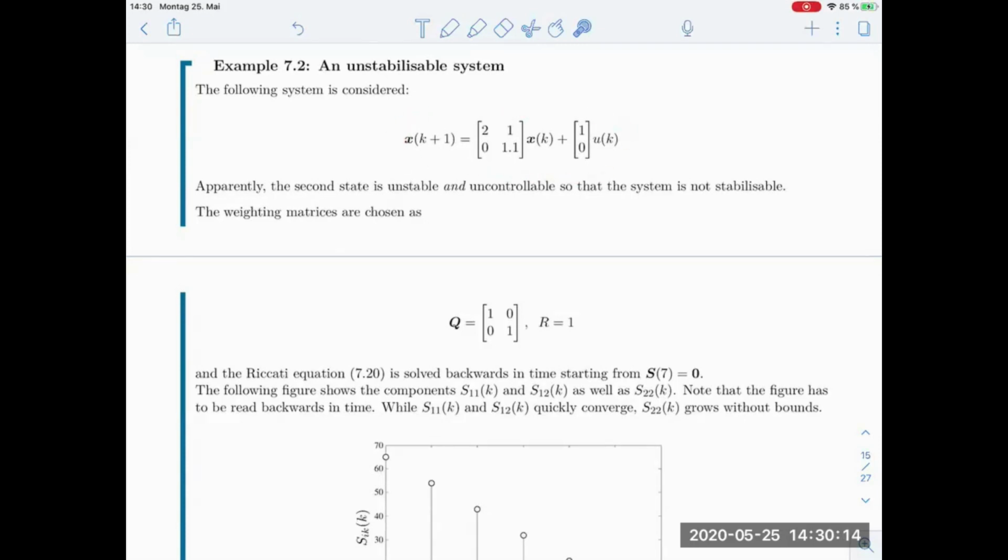We have this system. The system has 2 unstable eigenvalues. Well, how do I know that? Remember, we spoke about if a matrix has a particular structure, let's say A11, A12, a 0 block, which goes to the main diagonal, and then we have A22. Then the eigenvalues of such a matrix are the eigenvalues of matrix A11 union the eigenvalues of A22 because of this block of zeros here. All right, so that's one quite useful result from linear algebra.